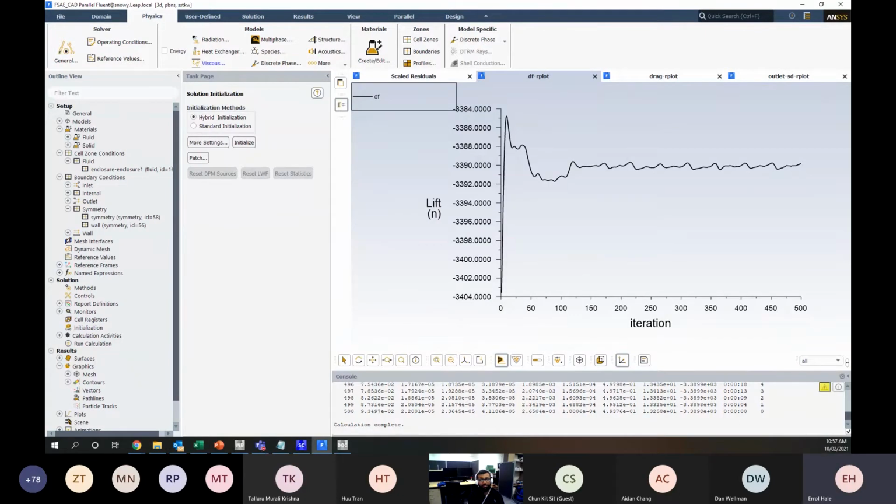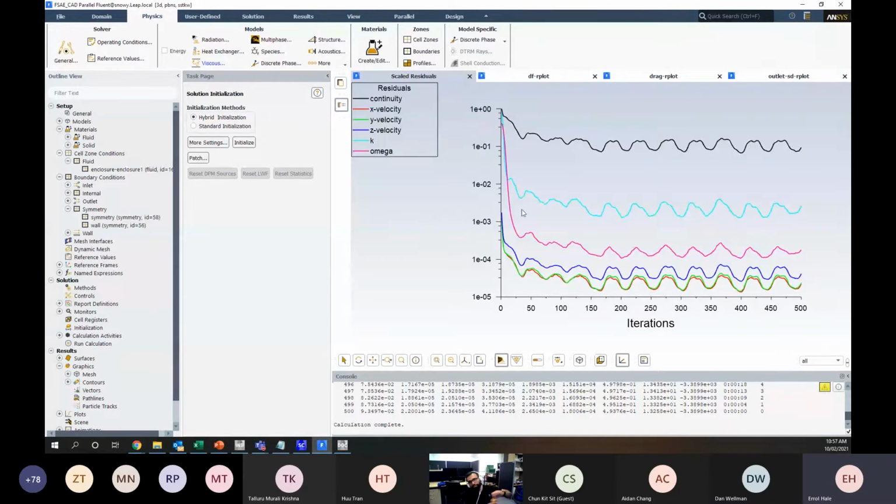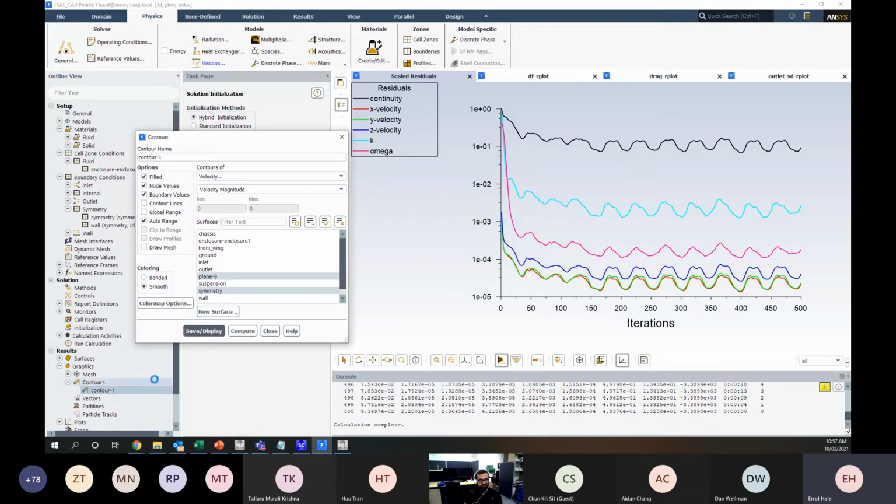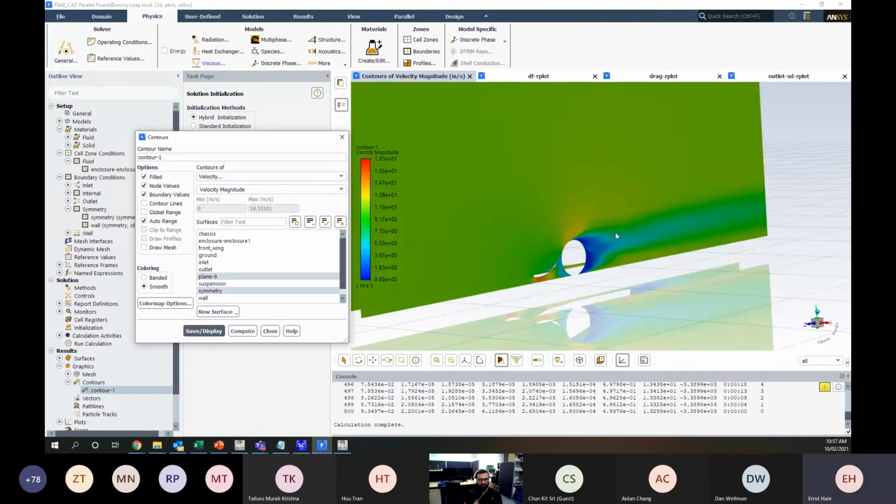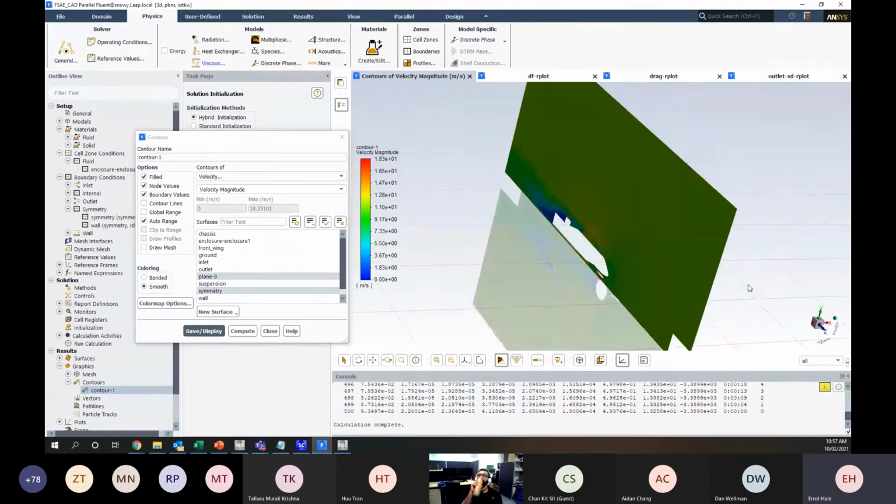So the use cases for K epsilon and K omega are anything. Most industrial flows will use K epsilon and K omega, unless you need to do something like this aeroacoustics case. Now, before we go into this aeroacoustics case, which is using the SBES method, we're going to look back at our convergence behavior of our model. Okay, so this is our vehicle model, just to remind everybody what it looked like.